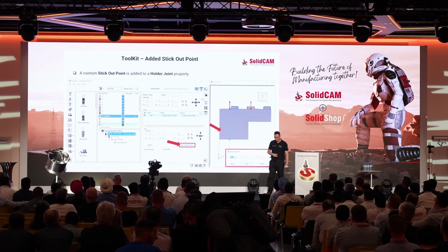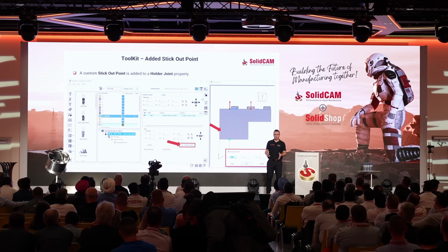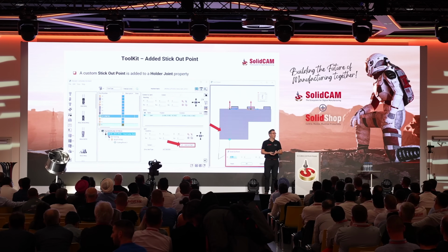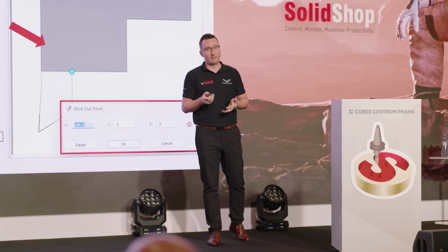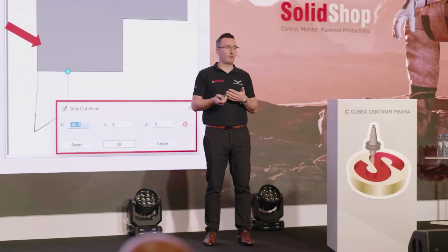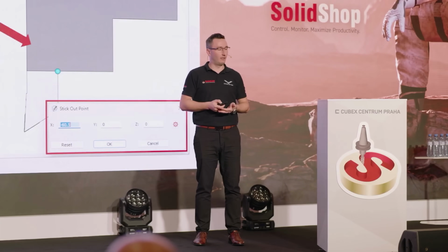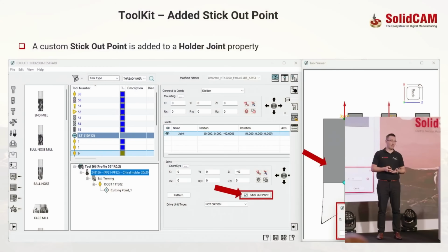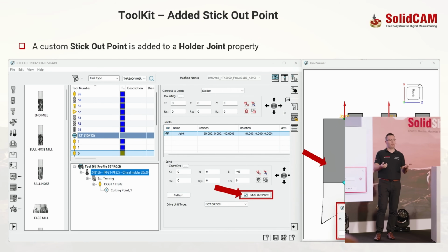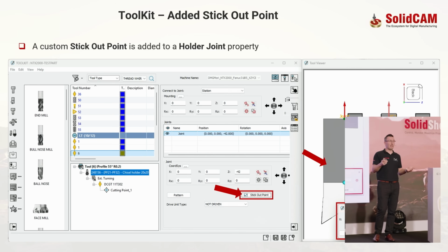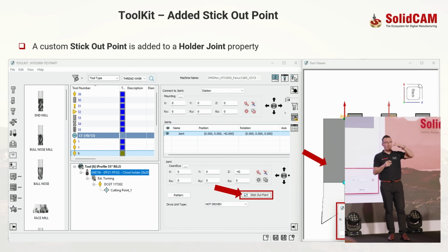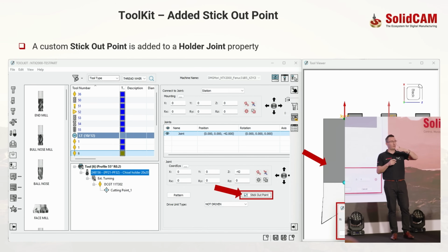Oh, my favorite. In milling, we have the outside holder length. That's fine, super, but it's not that intuitive to have a similar feature also in turning holders. Yes? So it's not easy to analyze what the stick out length is on turning tools, especially if you have very custom holders or very specific geometries. It is really unknown to the software whether it is the last geometry on the holder that is used or not.